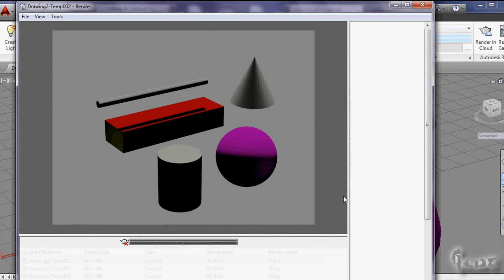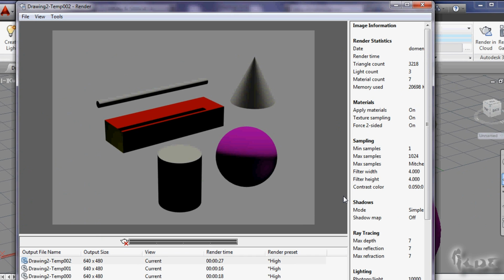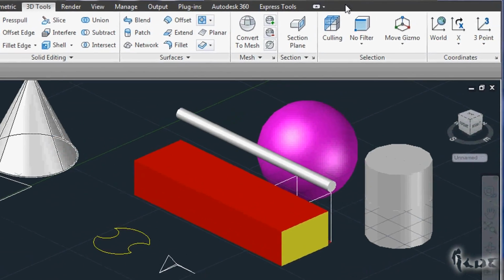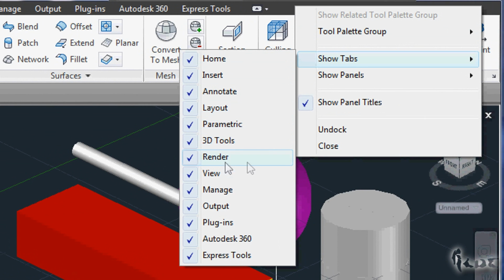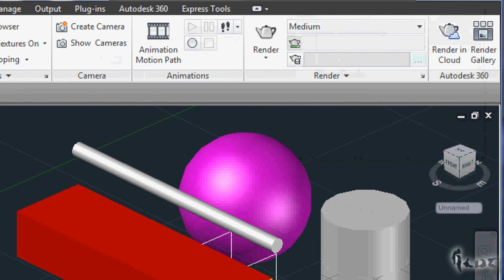Let's see how to render your workspace. This is used to have the final graphic idea of the project you have just built. Go to the render window or open it by right-clicking on the black space on the right and going to Show tabs and then to Render.